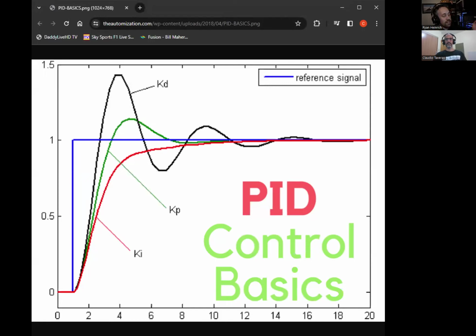The red line here is an undershoot, but I actually prefer that to the one that they're probably thinking is ideal. That 0 to 1 on the screen here is kind of like what I was saying from 0 psi to 12 psi, just a random example. And what we would want is, let's say our target is 1 on this picture, closer between the red and the green lines, where it gets as close to the blue line target as possible without overshooting or dancing around.